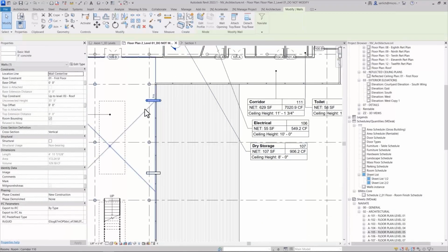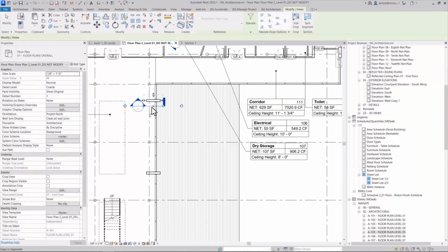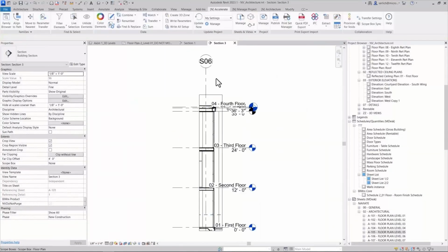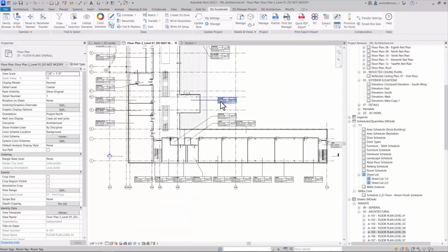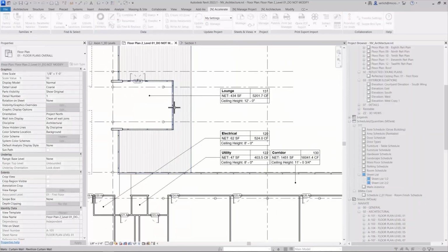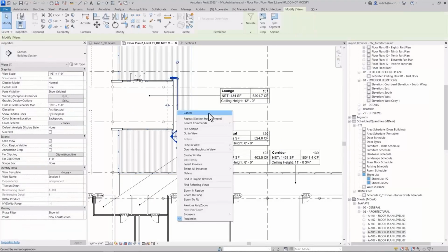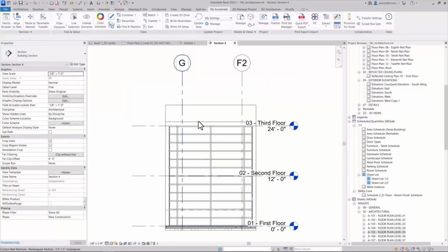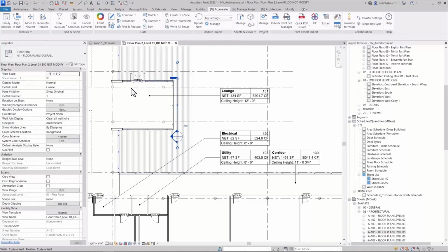First, by clicking a reference line within the element and then clicking on the side which you want to create the section on. Makes it really easy to create sections across walls, and then even while I'm working on different designs to create a section. It does encompass the entire element, so even if that element is crossing multiple levels, it will create it. And like I said, the greatest part is that view depth.